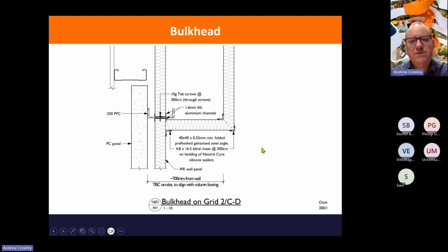And the side ducts were also formed using the PIR structurally insulated panels as well. So this is the connection. The typical arrangement for a warehouse is you have a precast concrete panel up to what I call a dado height. You have a girt supporting or restraining that, and then on top of that we can build our duct.